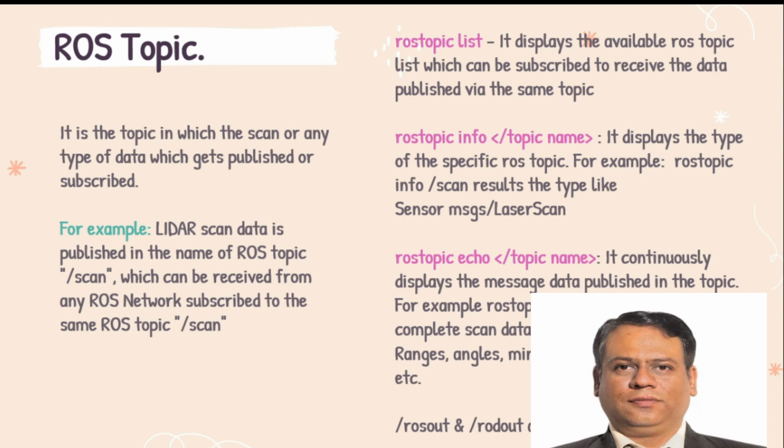And if you want to know about a topic's information, for example here /scan is going to transmit the data of angle and distance, right? If you want to identify this topic's information, you can pass the command ROS topic info followed by the topic name, which means /scan.